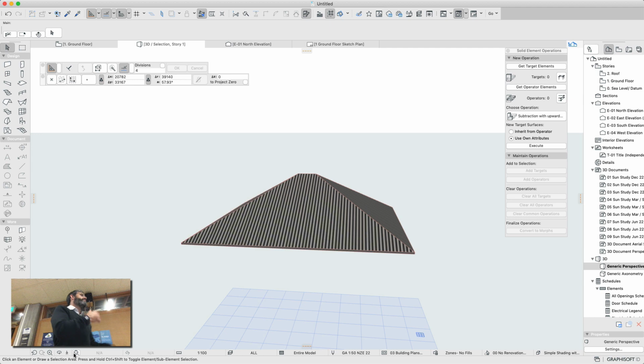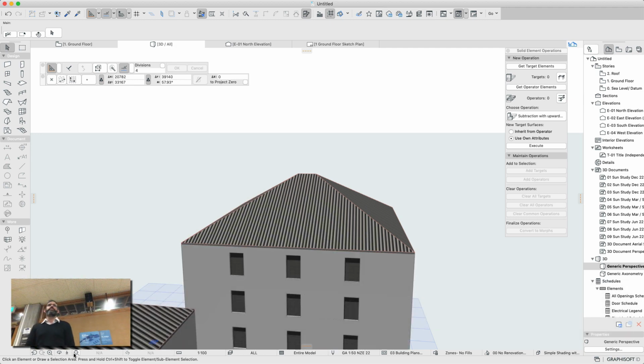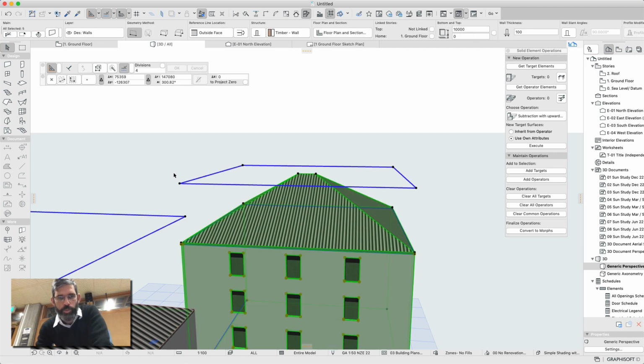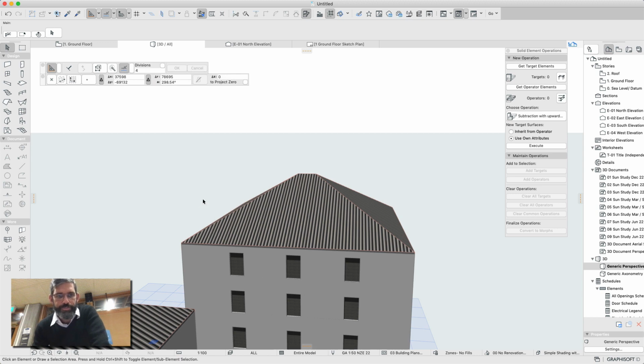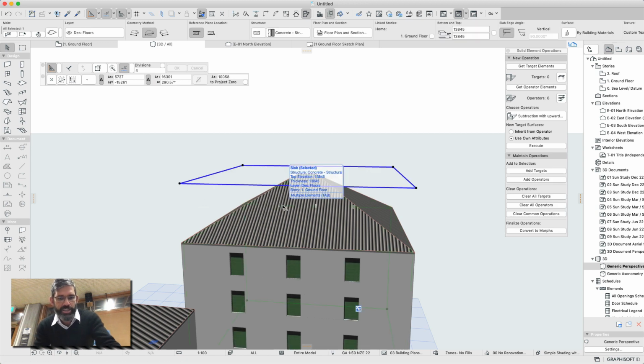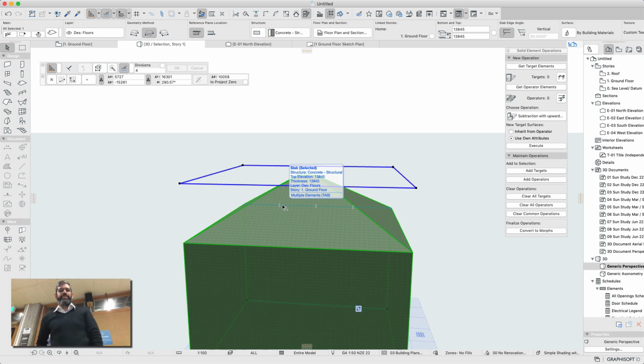Otherwise, just select it. Oh, that's right, sorry. If you have nothing selected and now you go F4 again, everything else just reappears again. Okay? So you select something, hit F4, takes just that element into the 3D view. You can even do this in the 3D view. So if I go and select this wall, oh, whatever, I can't select the wall, but anyway. If I go and select just the roof, and I press F4, I just managed to select the slab, that's alright. That's cool, I wanted to see the slab anyway. And then I've hit F4 again, it resets it and goes back to how it was.